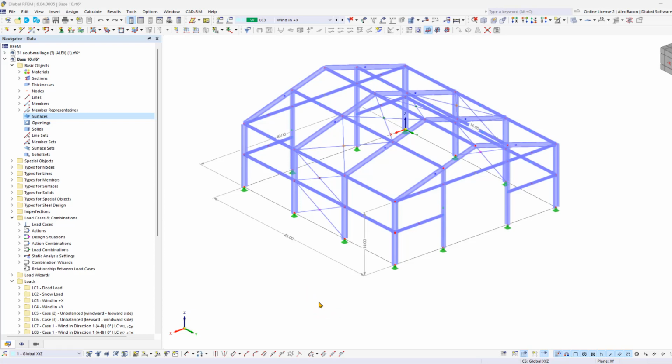This marks the final chapter of the steel hull loading tutorial. In this video, we will demonstrate how to create horizontal wind loads using load transfer surfaces. Before we apply the horizontal loads, we must create the lines to close the open cells, such as the gable of the hull. This step is necessary so that RFEM recognizes them as closed cells and loads them accordingly.